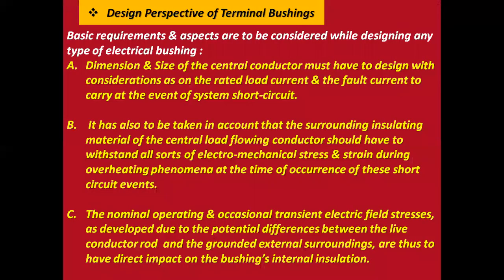Let's start with design perspective of terminal bushings. Basic requirements and aspects are to be considered while designing any type of electrical bushing. A. Dimension and size of the central conductor must be designed with consideration of the rated load current and the fault current to carry in the event of system short circuit.